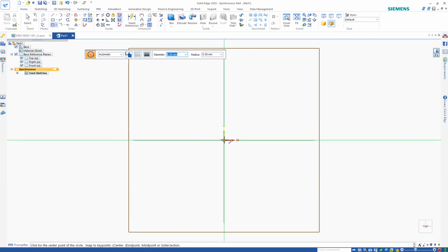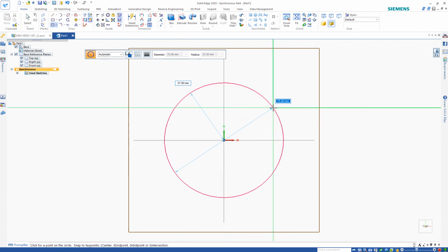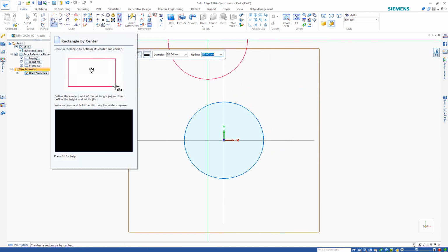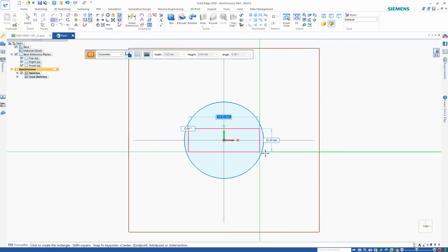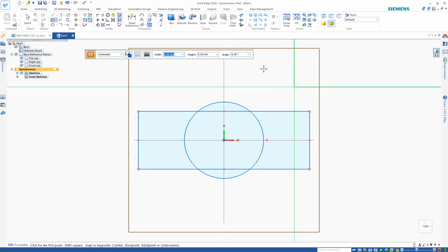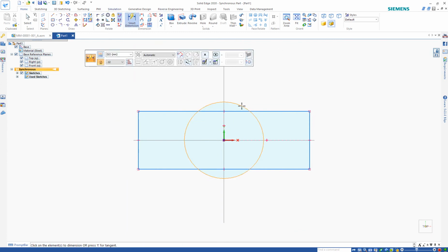Next thing you want is a drawing view. You can click here sketch view, or press Control H. Let's move to the sketch view. Lay down this circle from the center of the coordinate system, and we'll give the diameter as 50. Okay. Then we're going to draw this rectangle also from the center. Alright.